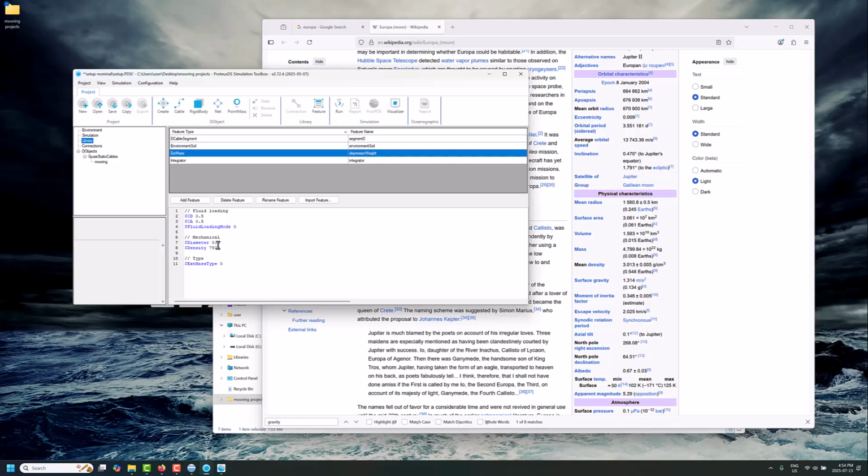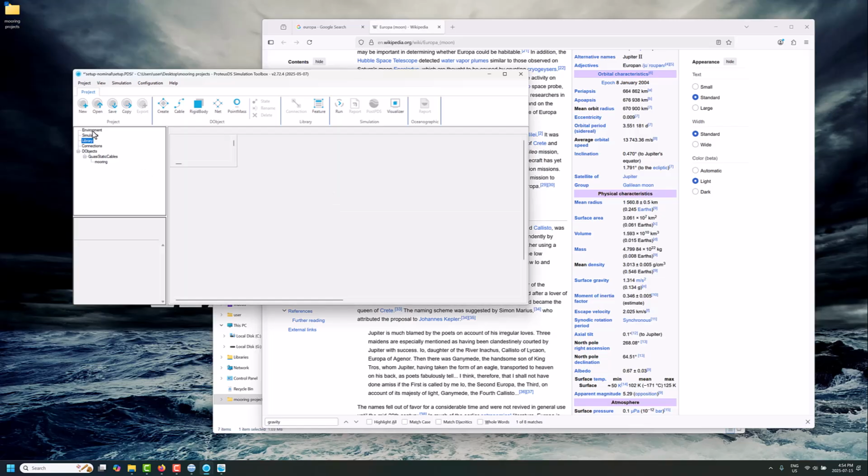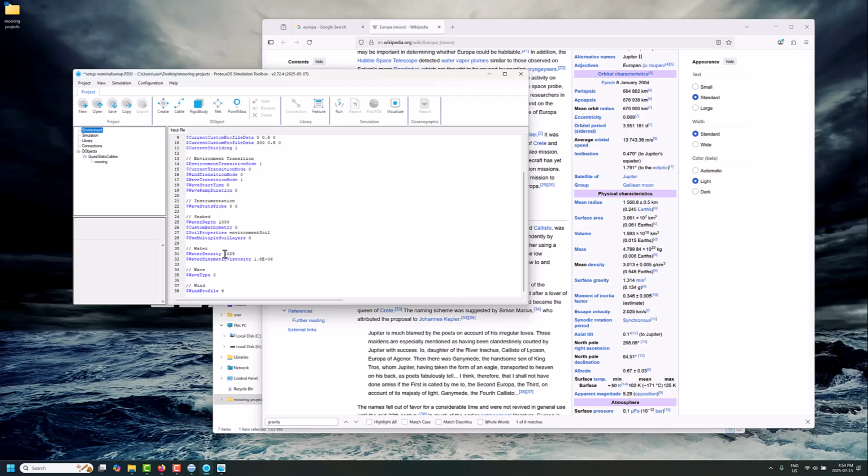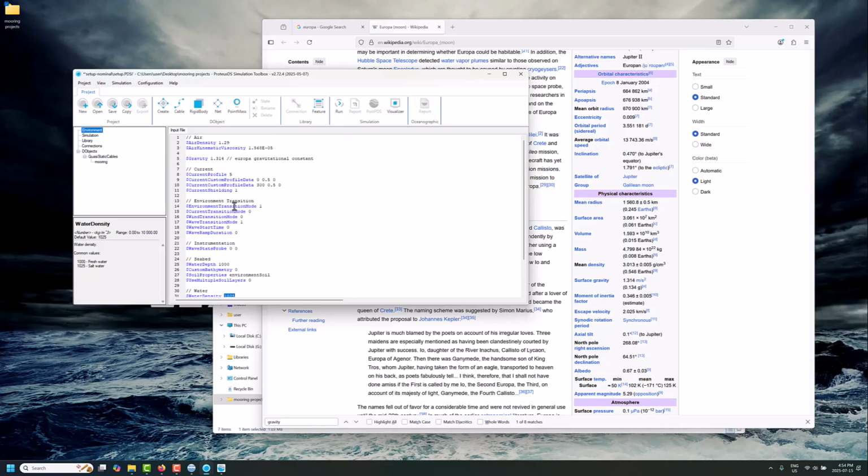The weight, the force from gravity, is going to now be significantly reduced because of the gravitational constant. Buoyancy, on the other hand, will still be a factor of that displacement of water volume, and you can set the water density in here. Maybe the density might be quite different on Europa, but you can make a change accordingly here. And then, of course, buoyancy is also scaled by the gravitational constant. So with the same current profile, with a much lower gravity, I expect to see a lot of deflection.